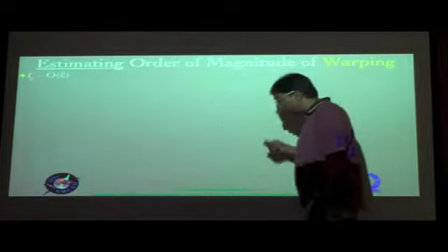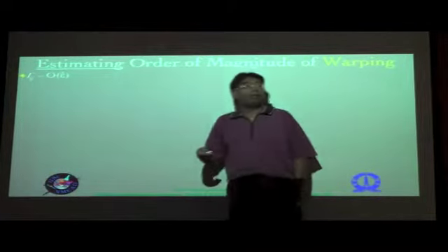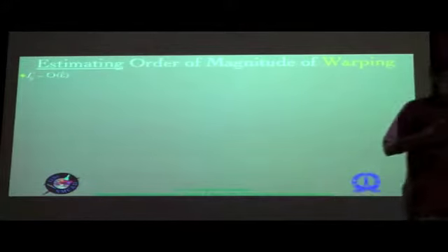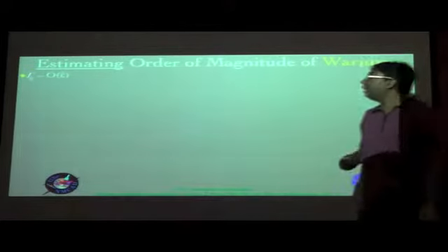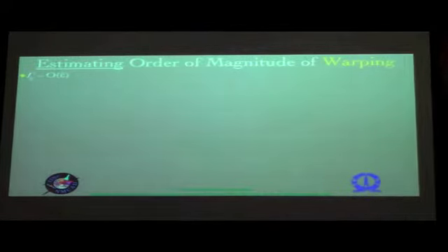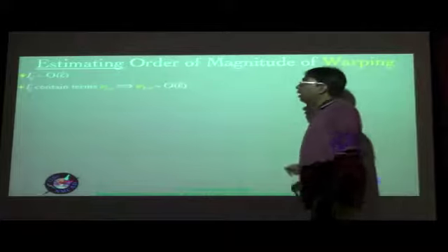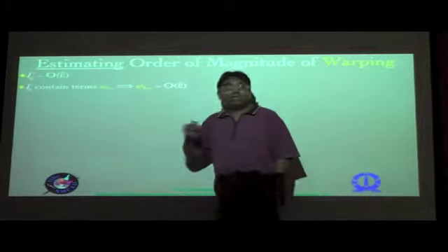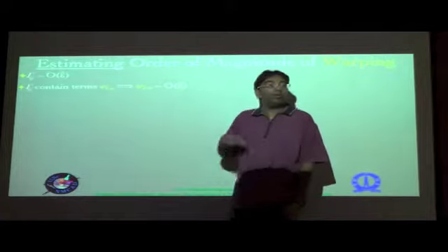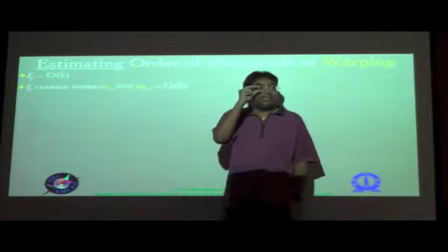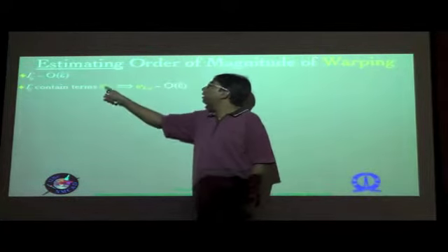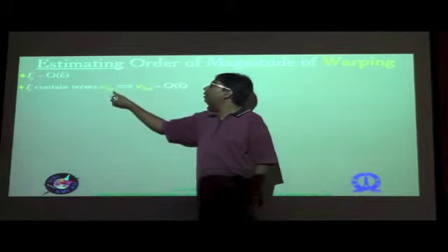Now, of course, the basic premise for it, as I said, is the fact that the maximum strain amongst all the components anywhere in the beam, again throughout the interval under consideration for a dynamic problem, is of the order of quantity which we shall denote as epsilon hat, just as in the previous classes. So some of the gamma ij's, the components gamma ij, when you expand out, you would see that irrespective of whether the definition is using the big B's or the big T system, it contains terms like the derivative of a particular warping measure number Wk with respect to x alpha.